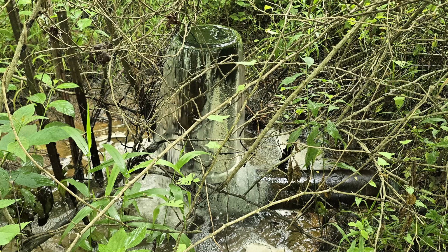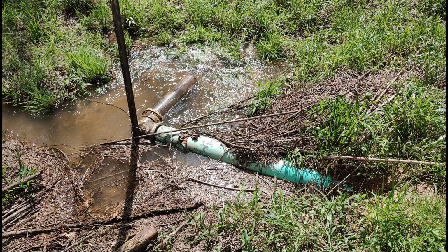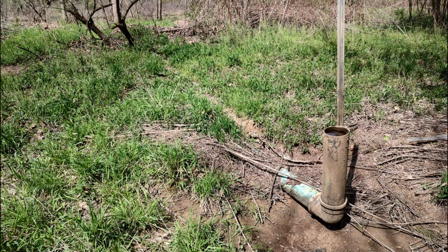Beaver have never blocked this type of water control structure, and no one has ever vandalized one, even though they've been installed on National Forest System land that's open to the public. Other advantages are that you can adjust water levels in the wetland and not get your feet wet, and the gaskets won't leak or tear or have to be replaced. The rubber gasketed drain pipe combined with gasketed 90-degree elbow that's placed on the backside of the dam is the most reliable and the cheapest water control structure I've found in my 47 years of building wetlands and ponds.